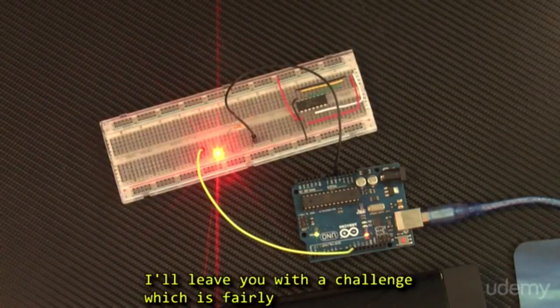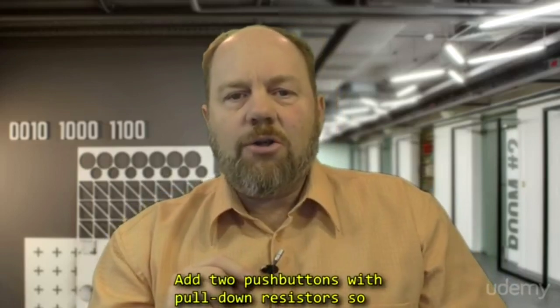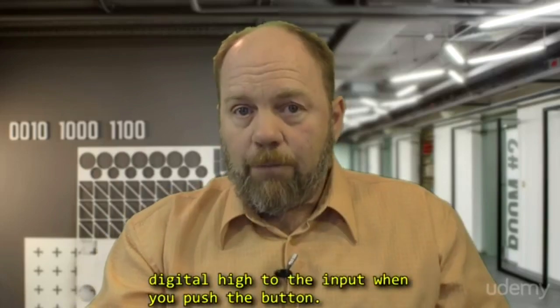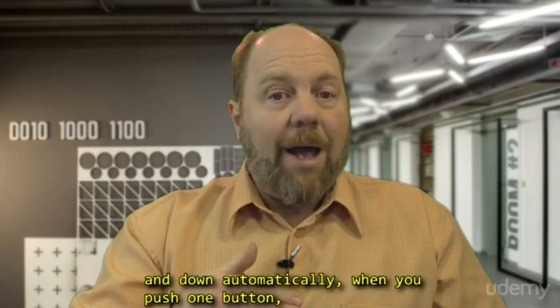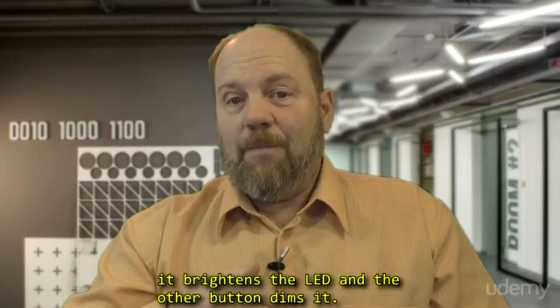I'll leave you with a challenge which is fairly advanced and will make you think through things. Add 2 push buttons with pull-down resistors, so they are active high buttons. That is, they send a digital high to the input when you push the button. Rewrite your sketch so that rather than fading up and down automatically, when you push one button, it brightens the LED, and the other button dims it.